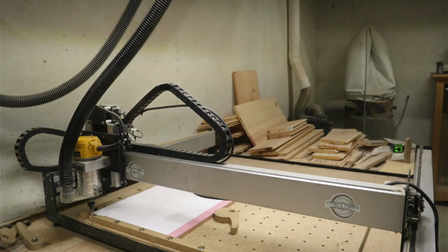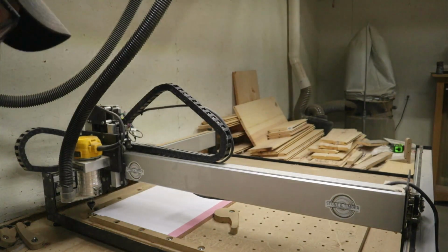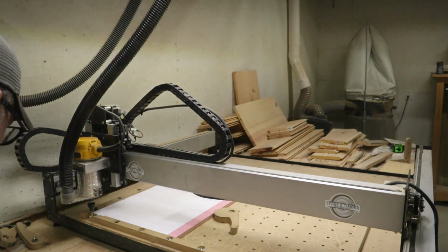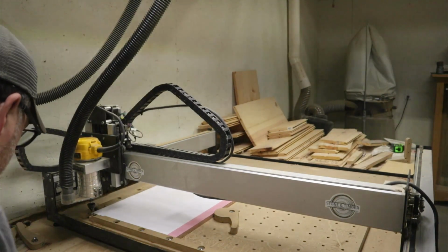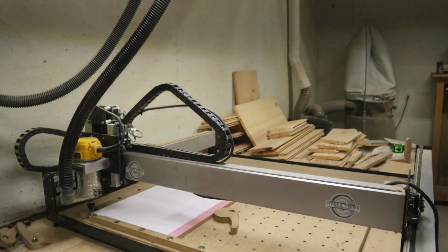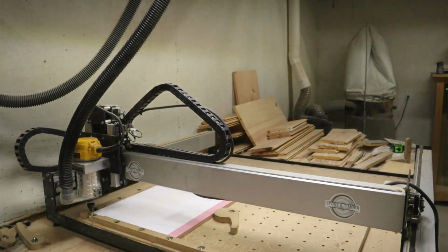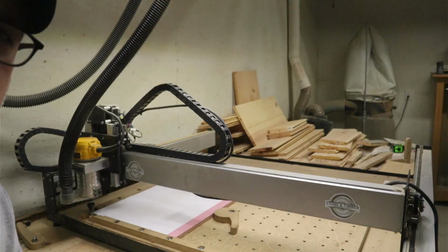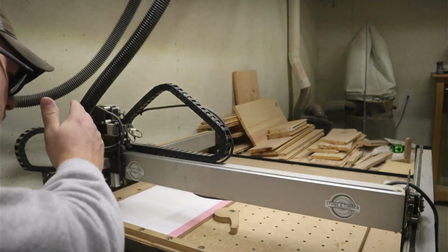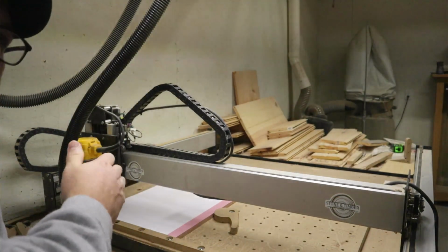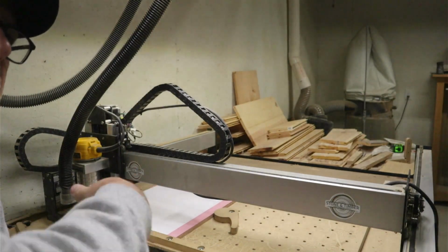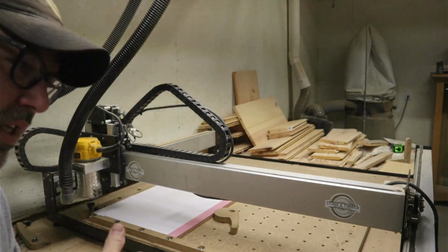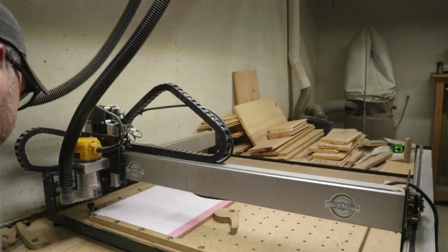And then I'll adjust how fast it moves again, and I'll just fine tune it there. So now it's moving a little bit slower. This is like 1/100th of an inch at a time. Now, the nice thing about this is I'm going to be able to set the XY to 0, and it's going to stay constant for the second portion of this cut. The only thing that's going to change is our depth.